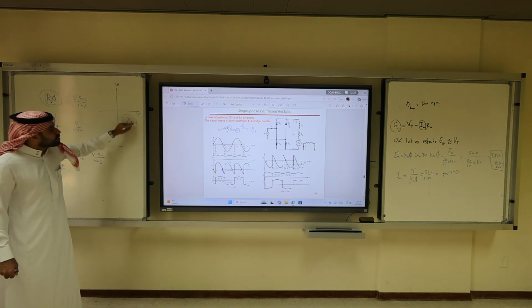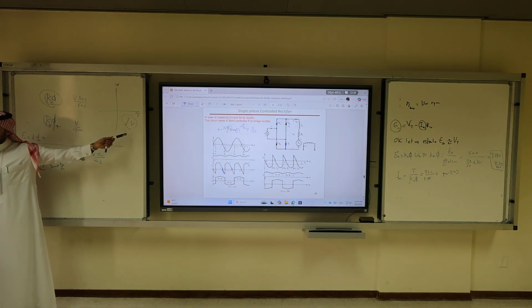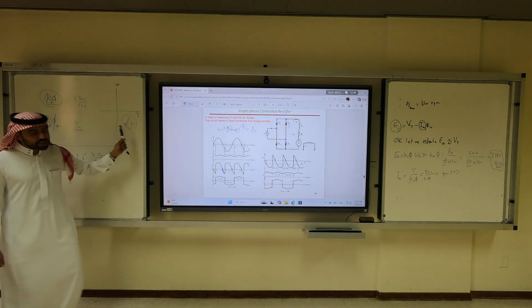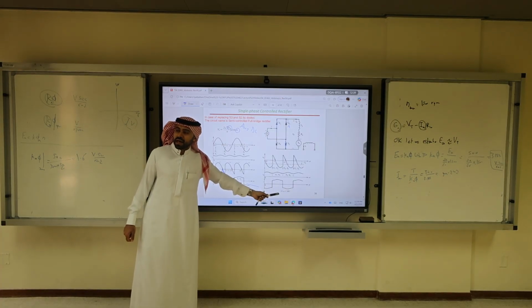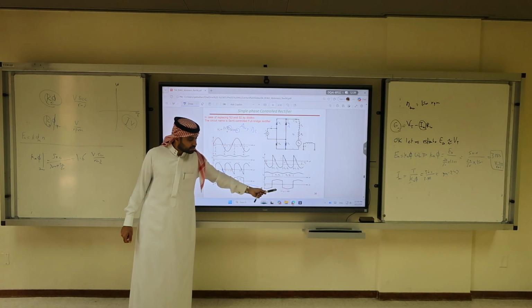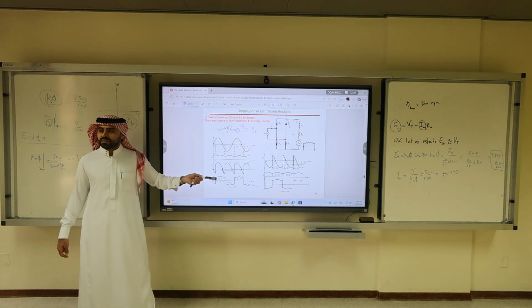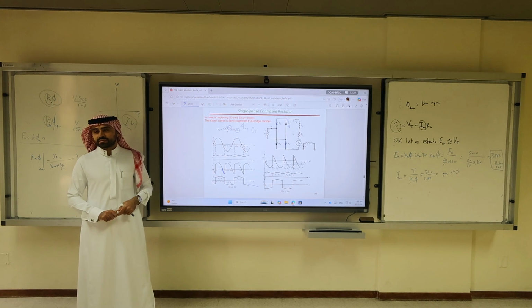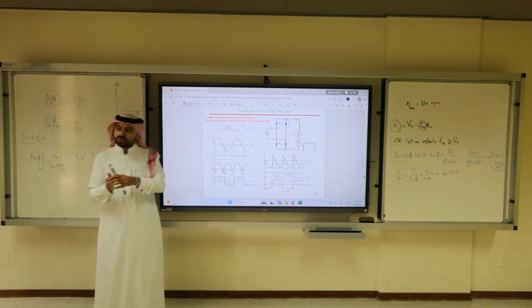We will talk about braking in the next few lectures, maybe next lecture or the following one. So we are here at what we call regenerative braking. One way to do regenerative braking, Osama, is to have a firing angle that's more than 90 degrees. And now we know how the Teslas work. Without power electronics, without Dr. Mahmoud Qassas, we cannot survive. And you can see how a DC motor can enter into dynamic braking.